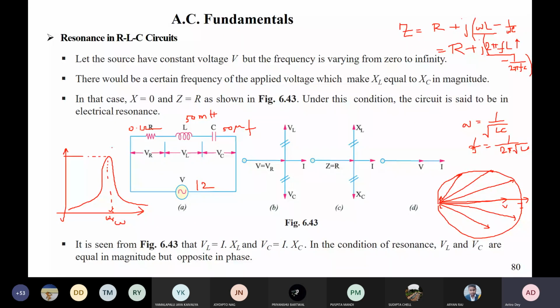If you apply a signal to this RLC circuit, and your signal is the current through it, then you will see that for selective frequencies, it gives you a high amplitude current. That is why it is called the acceptor circuit, and it is used in transistors, or even in the television set, in many places. Similarly, if you have parallel resonance, when we study that, we will see that it is called a rejector circuit.